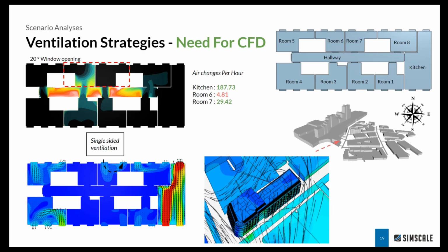But for the kitchen, you can see there is a direct flow which is coming from the southwest direction, and thereby you have a high degree or a dominant cross flow which is entering this window and then going out of the other side. You can also pretty much see why these corner rooms are ventilated well enough.